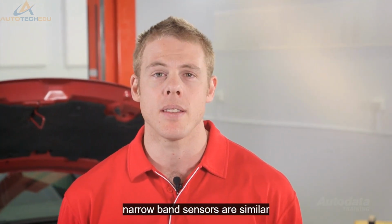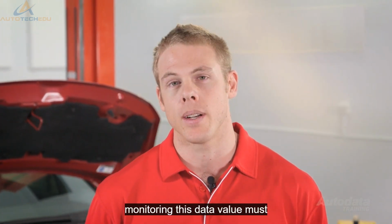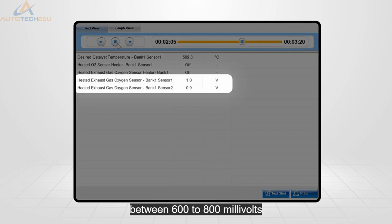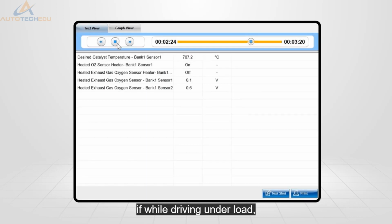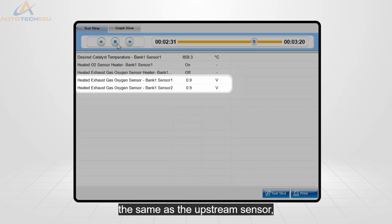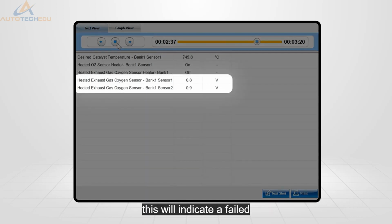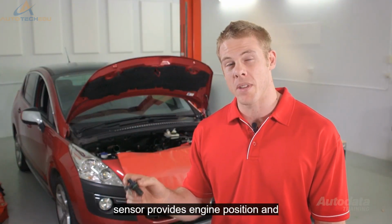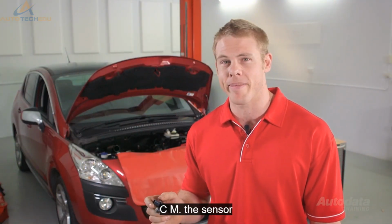Post-converter narrowband sensors are similar to upstream types. They're used for catalyst efficiency monitoring. This data value must be checked with the vehicle under load after a suitable catalyst warm-up time. The value will fluctuate between 600 to 800 millivolts when in closed loop with a correctly functioning CAT. If while driving under load the voltage cycle is the same as the upstream sensor, this will indicate a failed CAT.